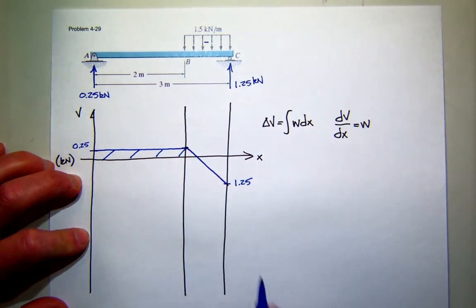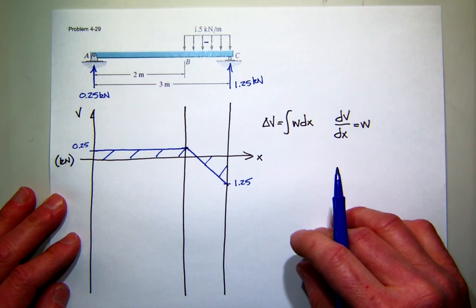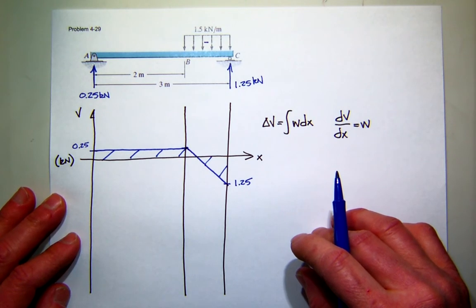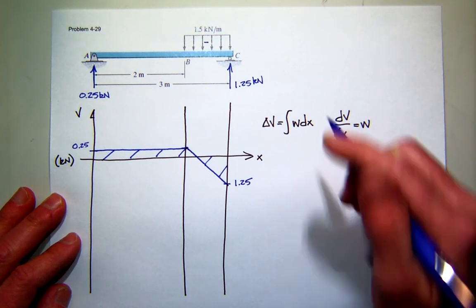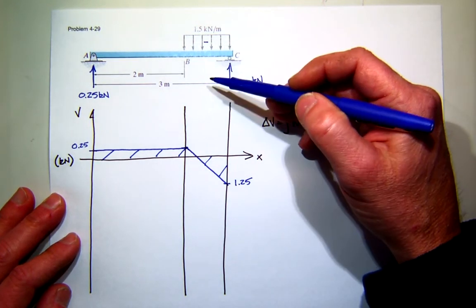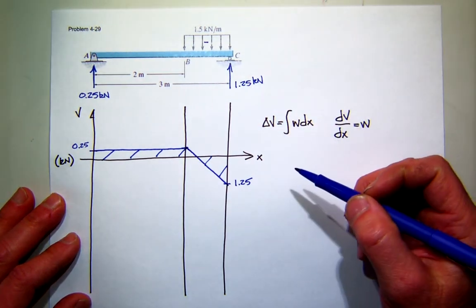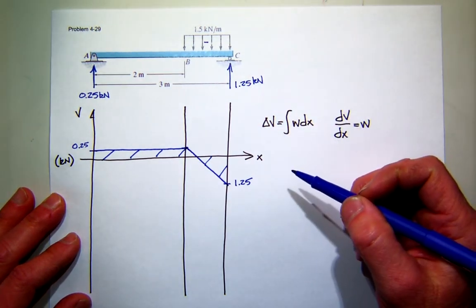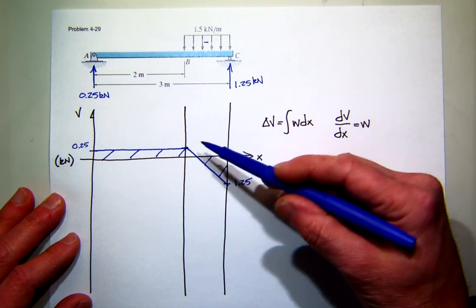Is it important that the line crosses at the midpoint of the load? It does not cross at the midpoint. I thought if you were to cut it at the midpoint between B and C and try to find the internal moment, would it not be positive on the left side and negative on the other side? Like if you were to draw another vertical line, would it not intersect right there? No. I do need to know where this point is, but it will not be at the midpoint.